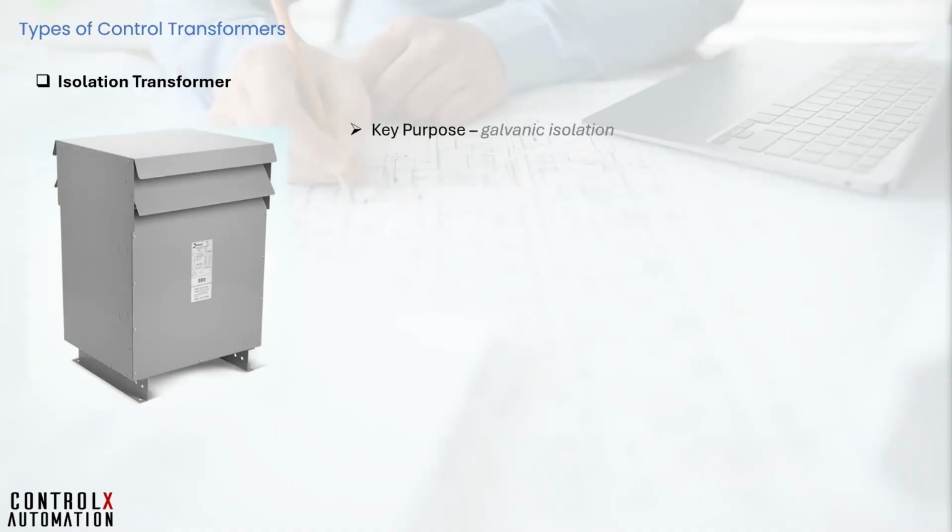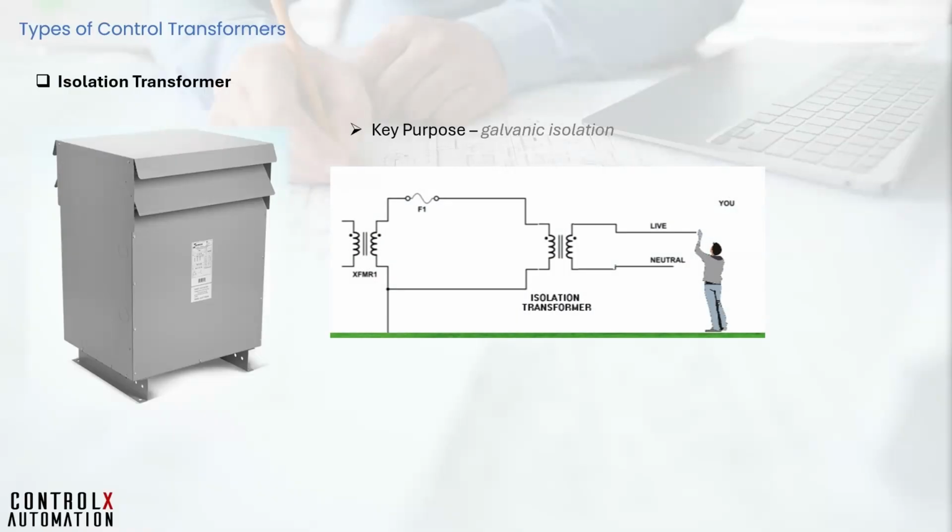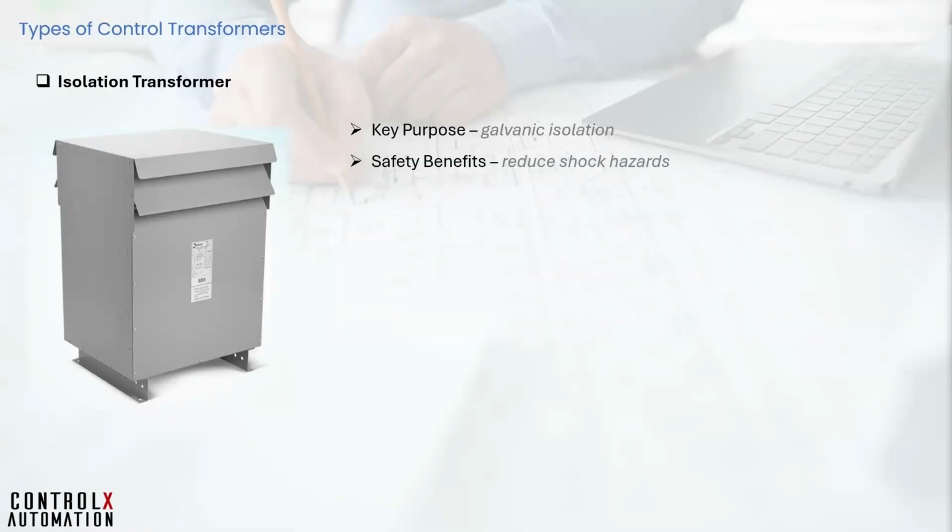The key purpose of an isolation transformer is to create a galvanic separation or isolation, hence the name, between the power source and the load, meaning there is no direct conductive path between the primary and secondary circuits. One benefit of this separation is that it reduces electric shock hazards by ensuring that the secondary circuit is floating and not directly connected to ground. So accidental contact with live wire does not complete a circuit through a person, although this requires that the secondary neutral is not grounded. Isolation transformers are widely used in environments where personal safety is critical, such as hospitals, laboratories, and industrial settings. By isolating the secondary circuit, they protect the individual from electric shocks by preventing the direct flow of current to the person touching a single live wire. However, I must point out that if you touch two live phases, then you're still cooked.